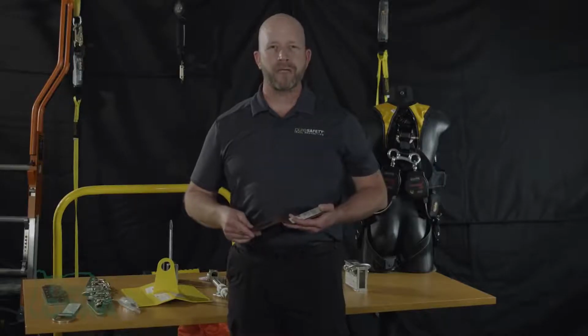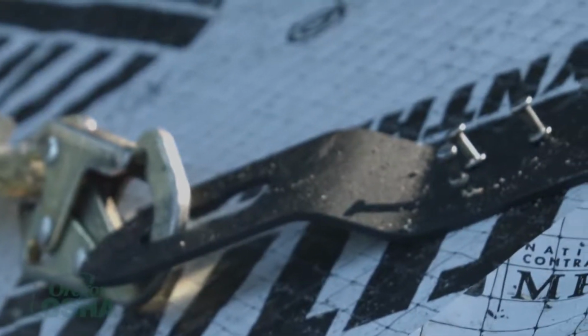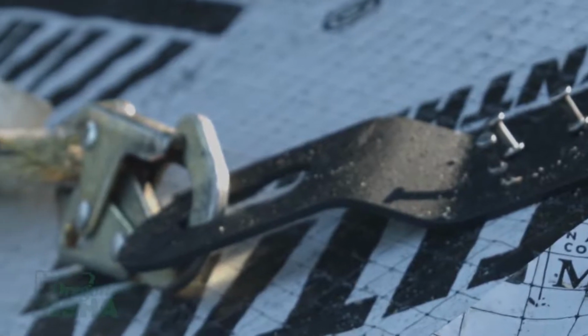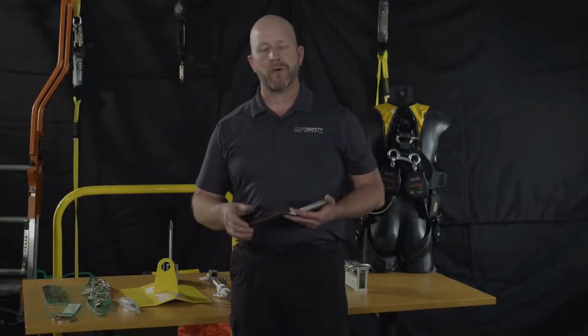So we'll talk through a couple different selections that are fairly common in the market. In the OSHA requirements, it does mandate that anchorages used in fall arrest be designed with a 2-to-1 safety factor, or 2 times the intended load, or capable of sustaining a 5,000 pound load. Nothing says an anchor has to weigh 5,000 pounds, merely that it be capable of sustaining that load, plus a